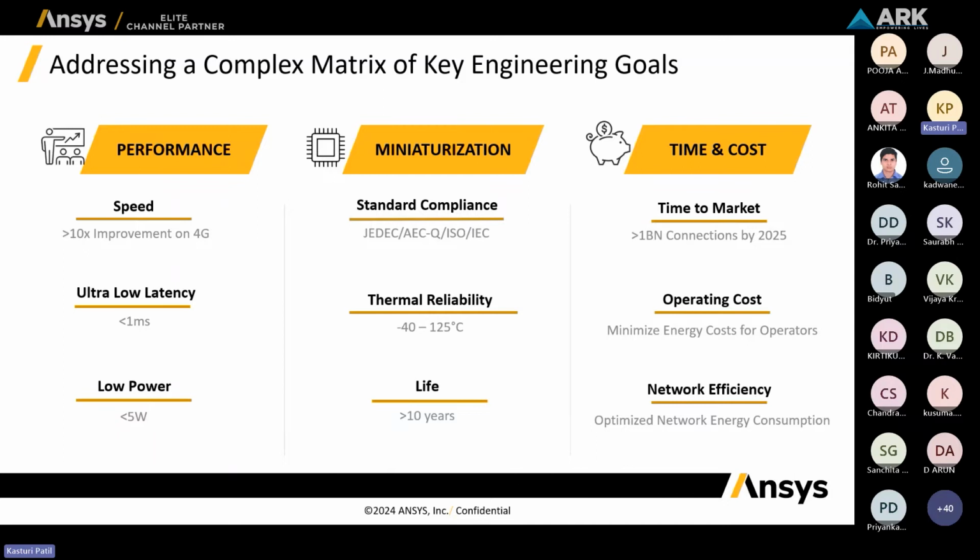It is used for package outline and thermal management purposes. AEC-Q stands for Automotive Electronics Council qualification, and these are specific to the automotive industry, used to ensure the reliability and performance of electronic components in automotive applications. The aspects included are temperature management, humidity, and mechanical stress testing.